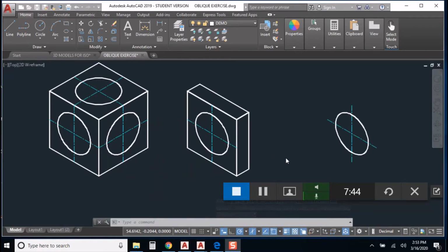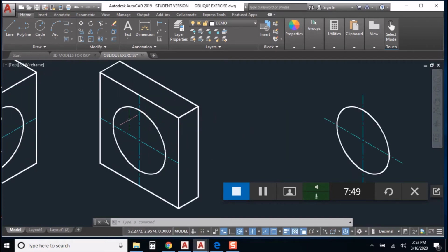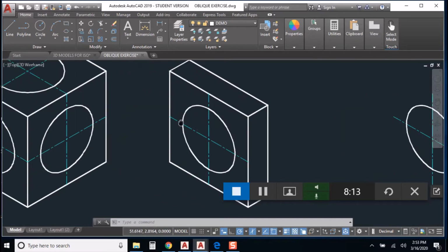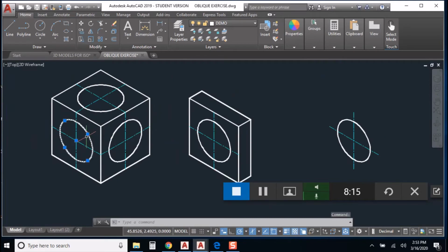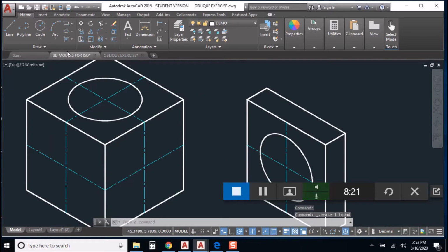Now, through the magic of special effects, I just threw a few more things up on the screen. Take a look closely at this figure here. So it's isometric. It's a thin piece of material. There's a hole going through it. Does it look complete to you? If we looked at that, we might think, well, it looks pretty good, but something seems to be missing. There's something wrong about it. And it's true. We should see a little curvature back here because this hole is only going through that much material. It's kind of thin. Over here, if I drilled a hole in the top, well, you wouldn't see the bottom of that hole, right?